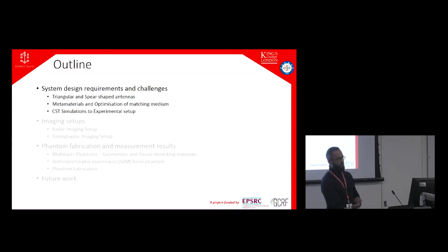Introducing lossy liquid brings another challenge. And that's the signal-to-noise ratio, which is limited by ordinary hardware. If we attenuate the signal too much, we cannot detect it, and hence we cannot process the results. So we have a lot of work to do on optimization of the dielectric medium that we're using to couple the energy, and to design a robust antenna, so it's repeatable. It's going to be working in different environments, sometimes in free space, sometimes in the lossy liquid. So it has to be very robust and compact, obviously.